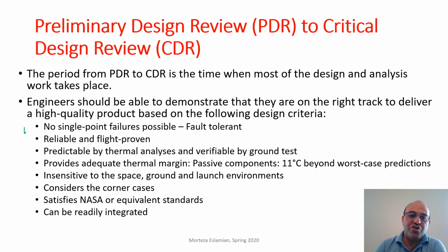There should be no single point failure. The design should be fault tolerant. It means that if something fails, if a heater fails, then a backup heater will come into the circuit. You may ask, how about if the second heater fails as well? Then that's based on the requirement of the design.